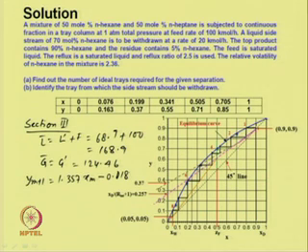We know the equilibrium data, since the relative volatility of the system is given. We can use this to plot the equilibrium line, and the side stream, which is given at the intersection point 0.37, is over here.